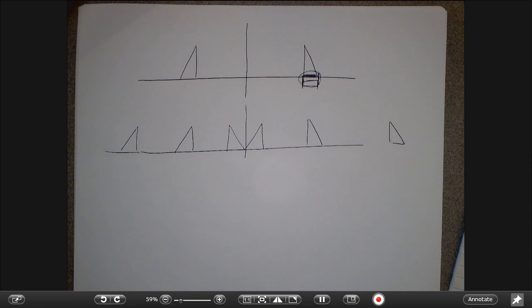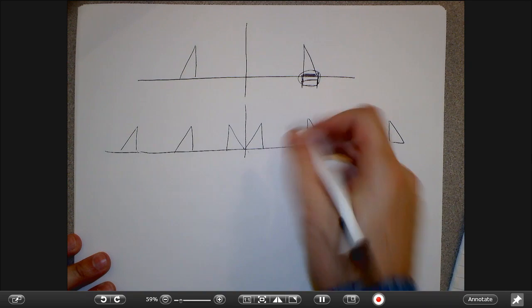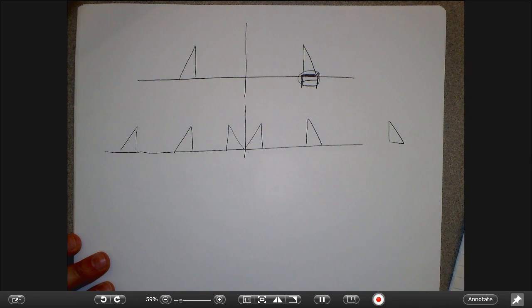So there are a bunch of little professorly homework problems about this. If you have a signal that looks like this, question number one is, what's the Nyquist rate? Question number two is, can you sample slower than the Nyquist rate and get a filter that you could use to do pre-reconstruction? And the answer is yes. You have to do that by drawing out where these copies can occur and making sure that no copy hits any other copy.